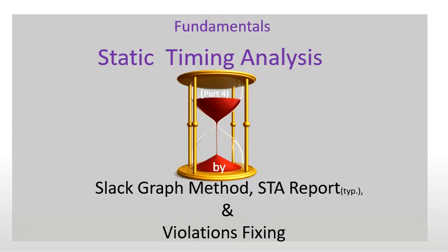This Part 4 STA presentation provides an overview of static timing analysis through the study of a typical timing path. We will examine the concepts of timing slack evaluation by the slack graph method. Also introduced is a typical STA tool timing report that presents the evaluated data. Finally, we will discuss common timing violations and the techniques used to achieve timing closure. So, let's get started.